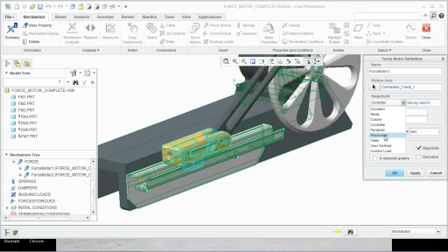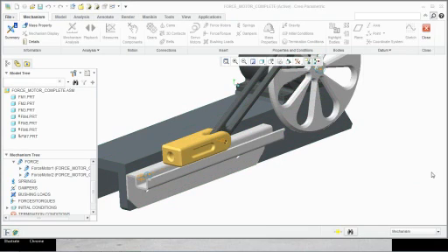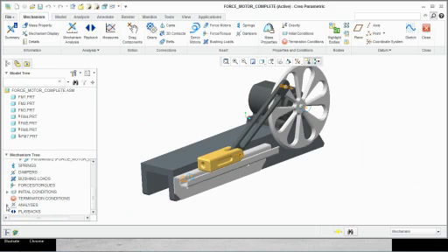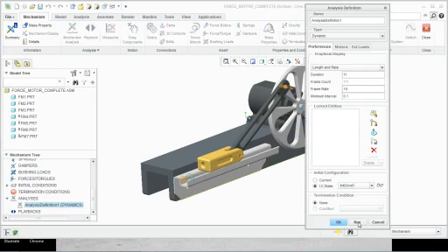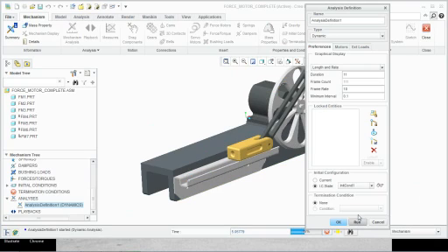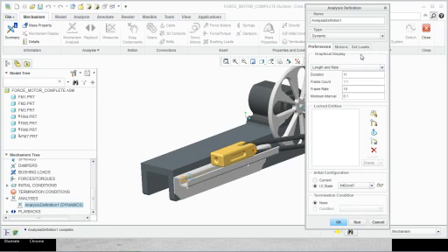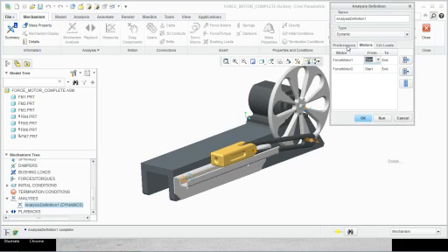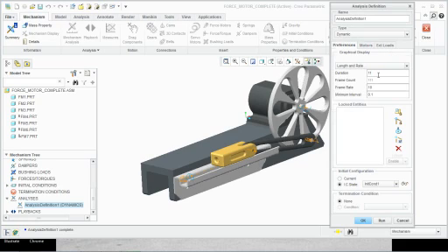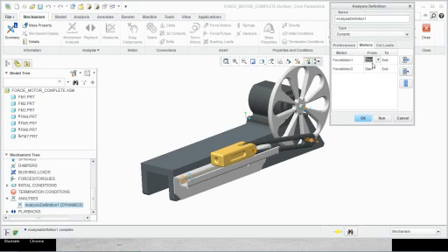And we can create this motor. Now let's look at some of the analysis results. I'm going to go ahead and run. You can see. Now another thing about this is that you can go here and say, you know what, for the whole analysis of 11 seconds, I want motor number 1 to start after 2 seconds, and then rerun the analysis.